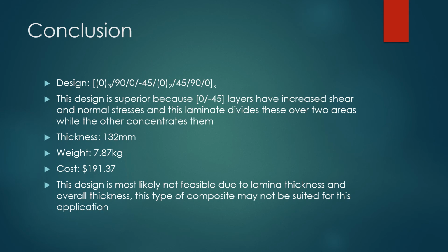Unfortunately, this design is likely not feasible due to the lamina thickness and overall thickness. Our laminate ended up being almost as thick as it was wide, which would mean that lamination theory would not hold, which was a big factor in one of our assumptions. This means that this type of composite may not be suited for this application in terms of forces. Additionally, because we had to move to 6 millimeter thick lamina, and most of the industry operates on 0.6 millimeter thick lamina, we figured that composites are probably not the best option here. Thanks, and that's all.